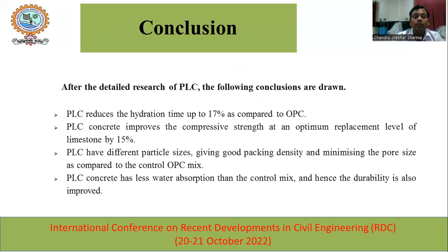Here is the conclusion of this presentation. PLC reduces the hydration time up to 17% as compared to OPC. PLC gives good packing density, so it minimizes the pore size.